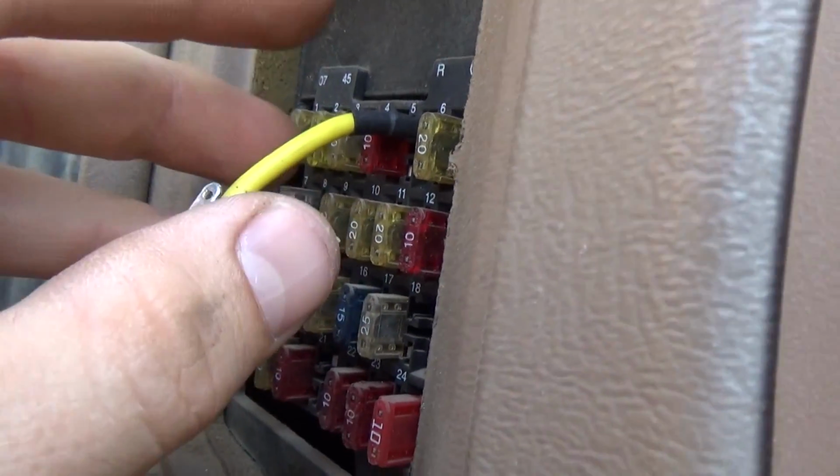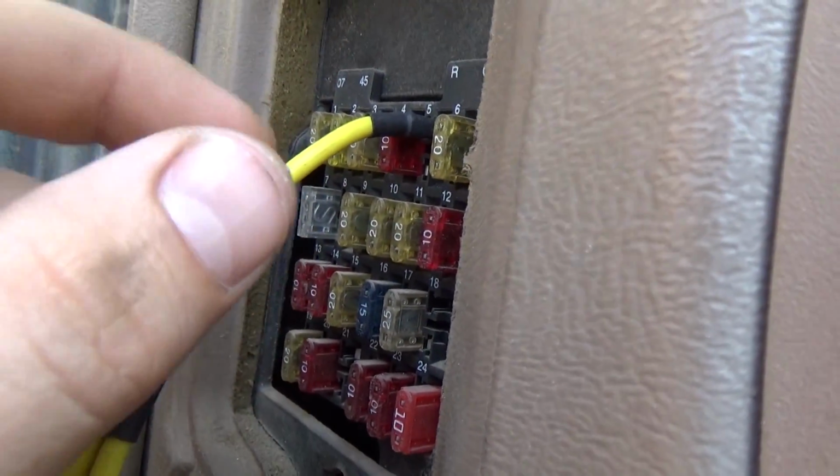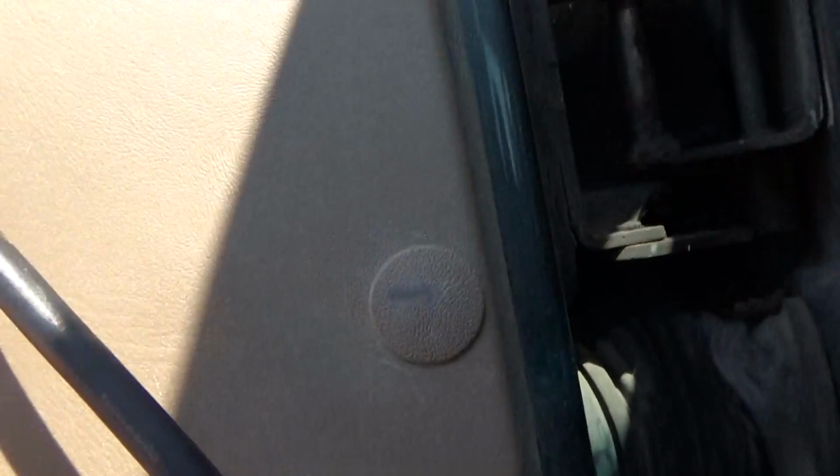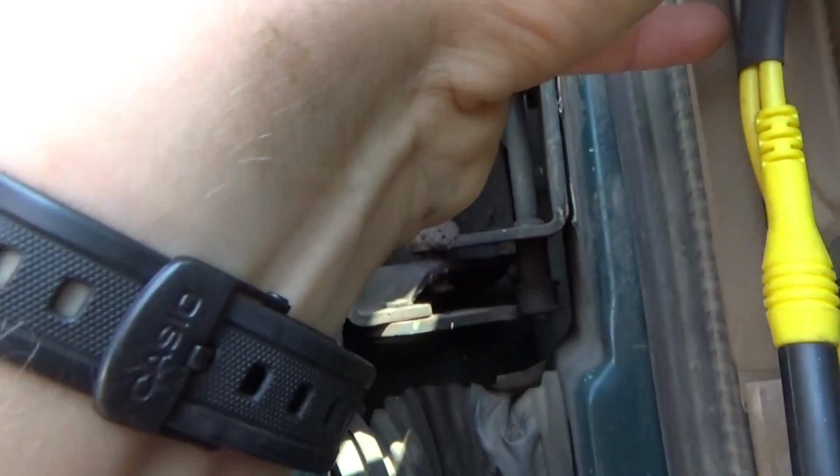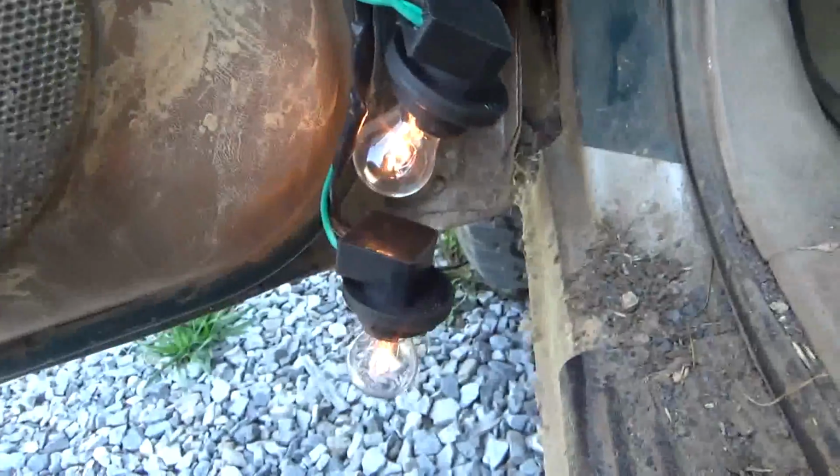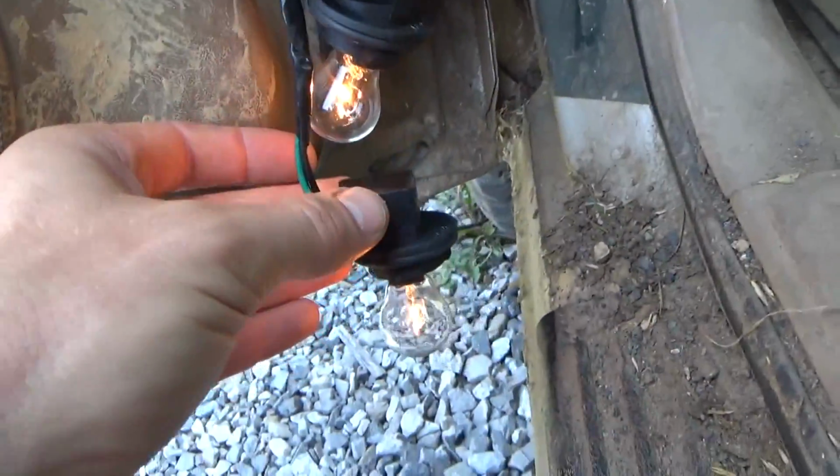So the top pin on fuse 5, that's the ignition feed. And now what we want to do is connect the test light to battery positive here. You actually hear the computer turn on there since we gave it a feed. But let's go to, alright, so that's how much current is going through our test light right now. It's not as bright, so there's no direct short to ground at the moment, but according to this fuse, there was a direct short to ground at some point in time.